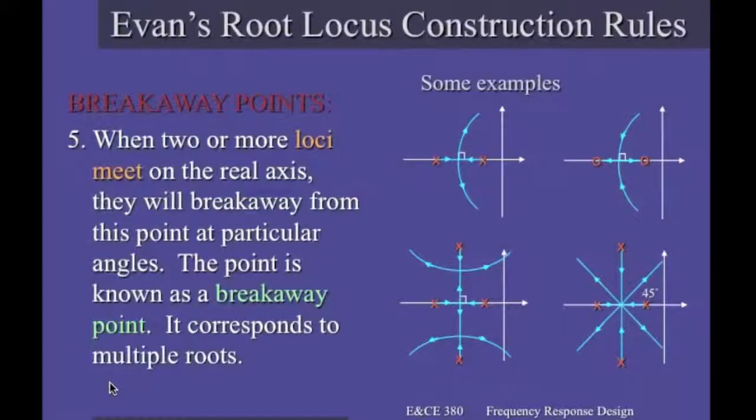We have, in some way, a cross of poles. Two of them being on the negative real axis, and other two of them being complex and conjugate. So why should the root locus be different when we have the same geographical mapping of poles?